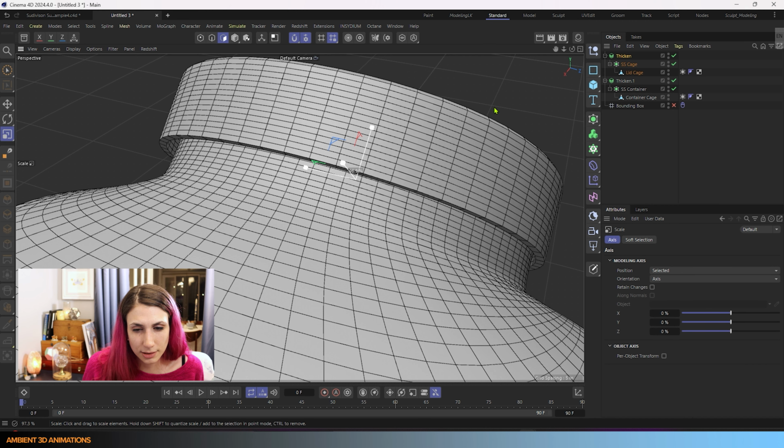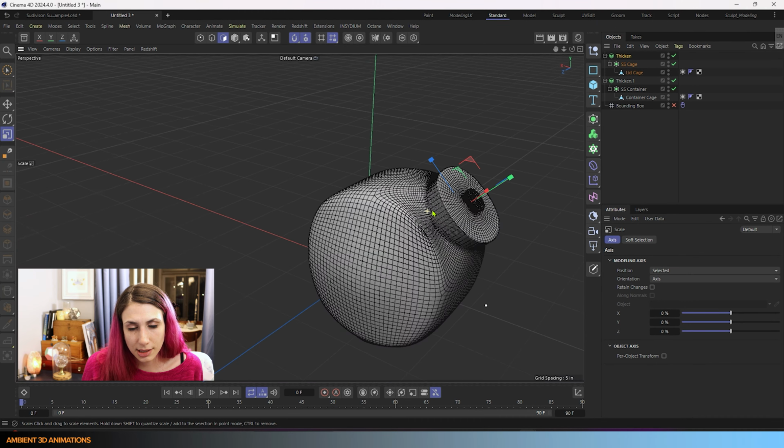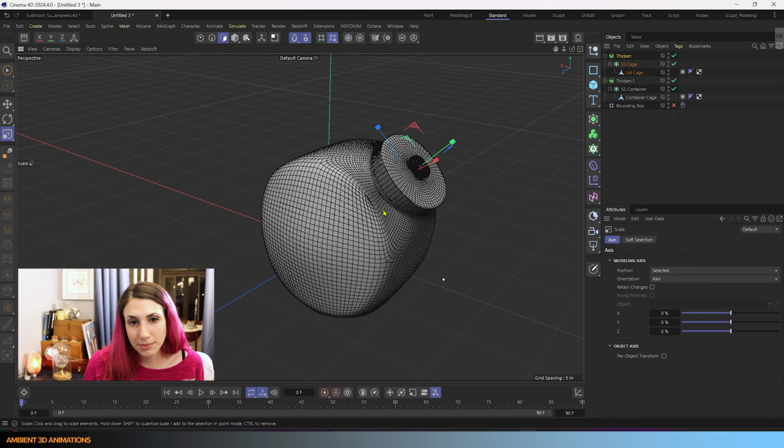I'll scale this in a little bit closer. We want a little bit of space between these because we're actually going to make it so that these have the part so they can twist on the lid. What we'll need now is a helix. So we'll grab our helix in here, but we actually want to add that to a similar place to where the grid was before.